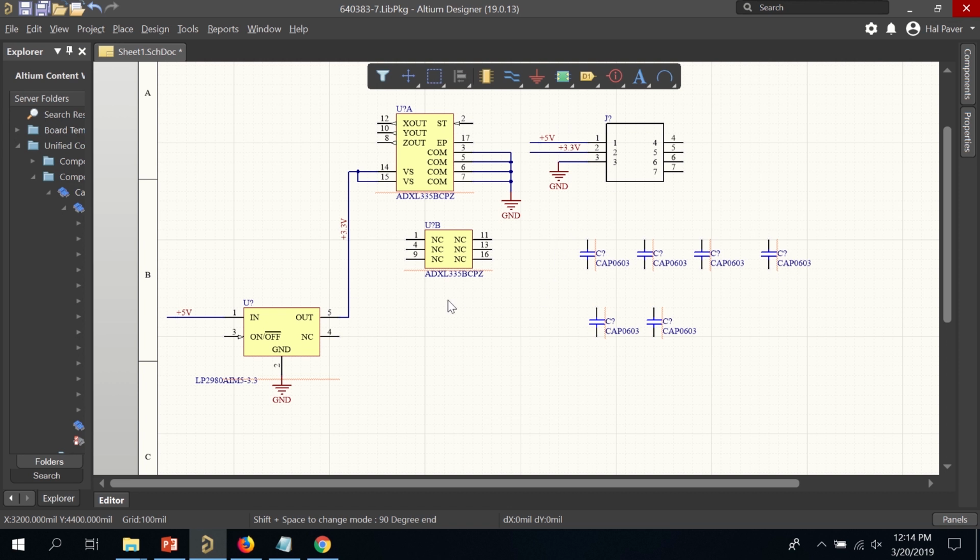Alright, so we are making the rest of the connections. I'm going to place a wire, and pin 3 will get connected to pin 1 and hit Escape. ST is our test pin, and that will get connected to pin 7. Now, if you start wiring all over the place like this, you might see that your schematic gets pretty messy.